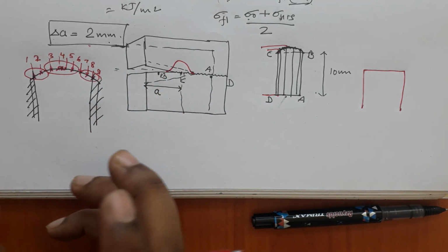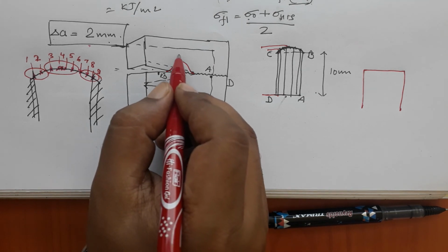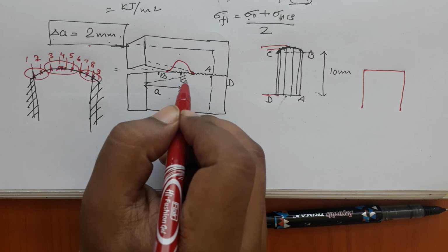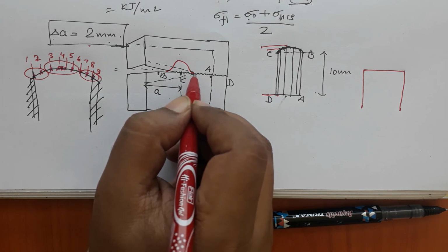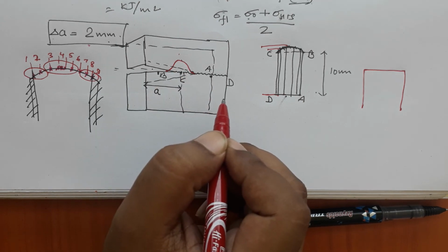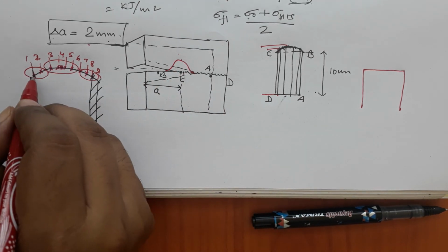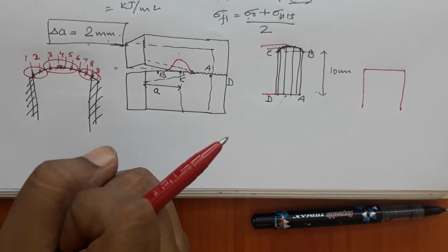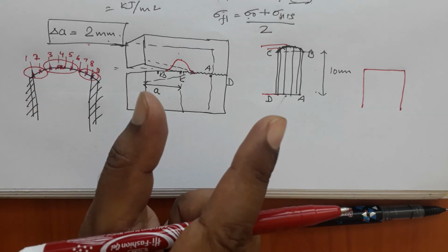So, the constraint is maximum in the center of the specimen and minimum at the surface of the specimen, and it has a gradual increase from the surface to the center, and because of which the crack has this shape, right. If you have more constraint, the crack will open up there very easily.